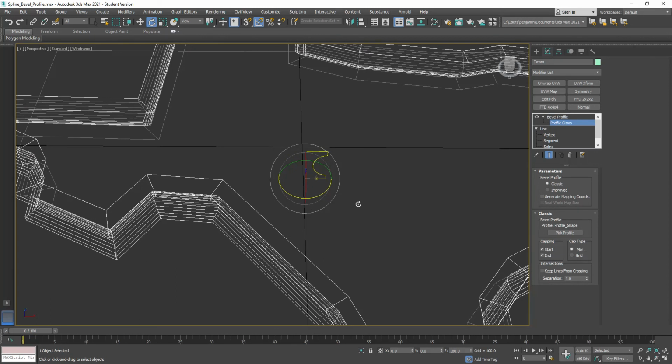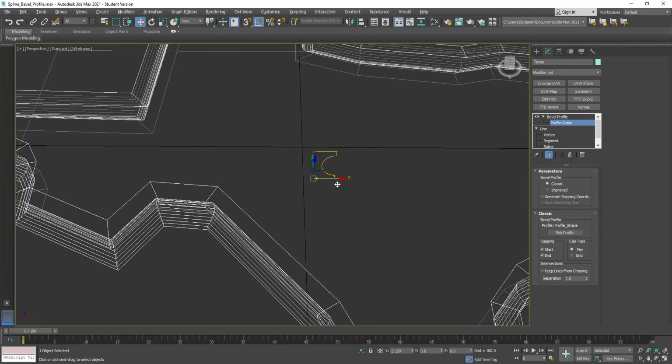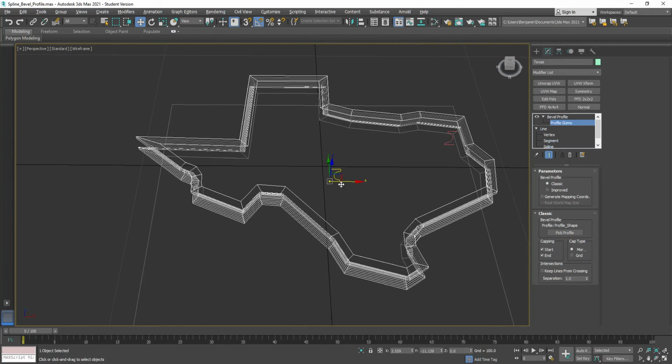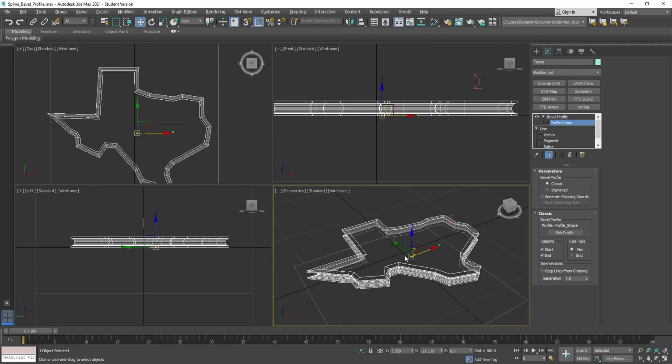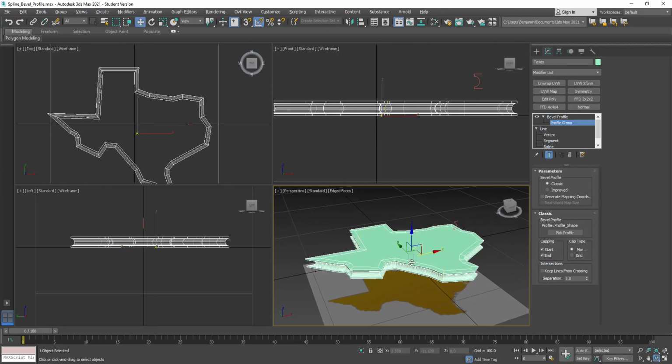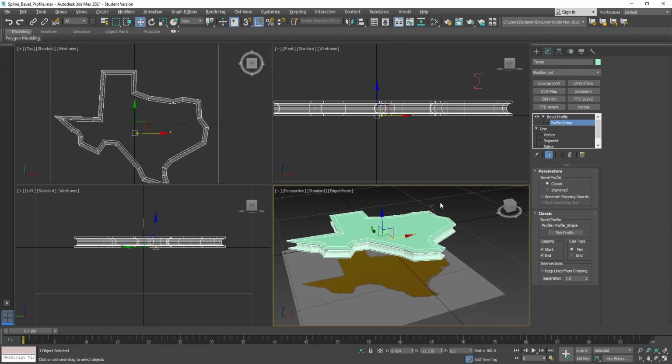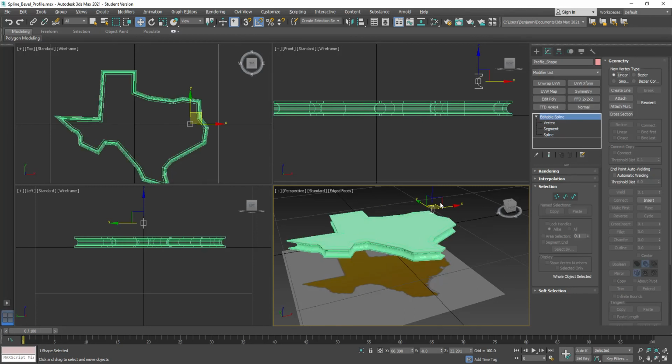So it is possible I could troubleshoot this by rotating where that sits here. I'm looking down, and as I rotate this, I'm looking at the Z value at the bottom, so I'm making sure it's 180. And I can move this out then. And so there's ways to go through and troubleshoot when you run into problems working with Edit Spline. Let's undo both of those moves.